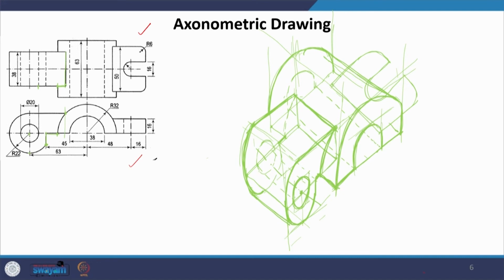So, what I can draw is I can raise this, which is this height at this point, or I could also arrive at this point in the elevation, which is this line which I drew in the plan, take the height which is here. So, I just took the height here, draw a parallel line, which is what we will see if we were to see it. This is going to be at the back and we won't really see it, we can just increase the height, and we will arrive at the radius, which is where it has to be from this level.